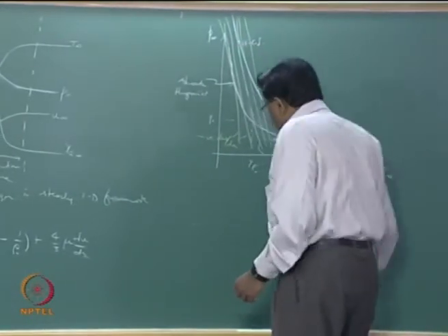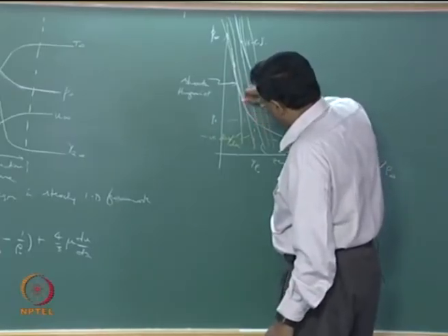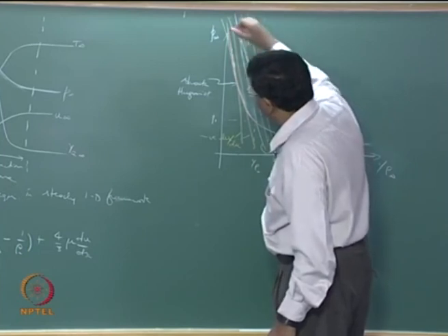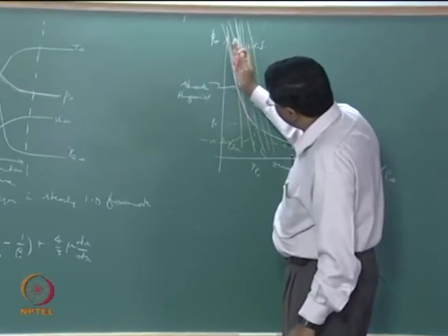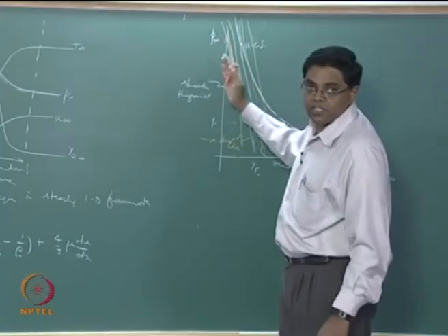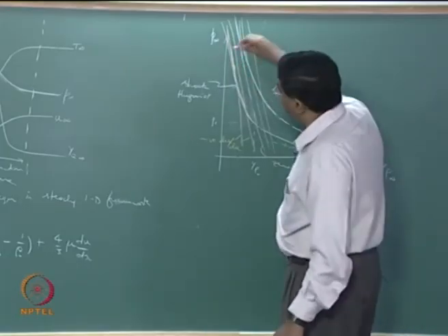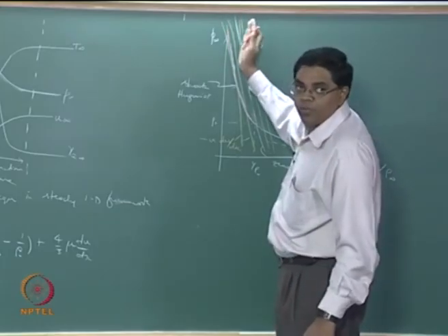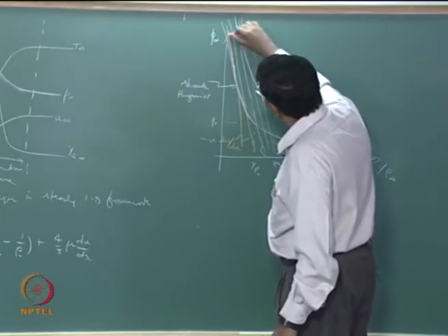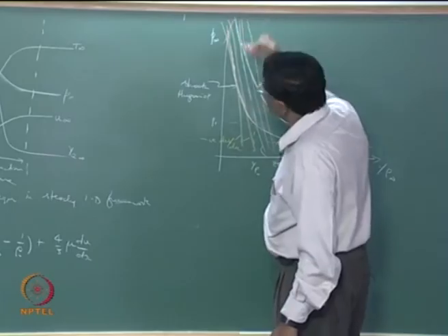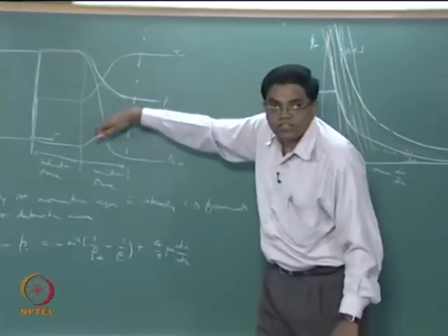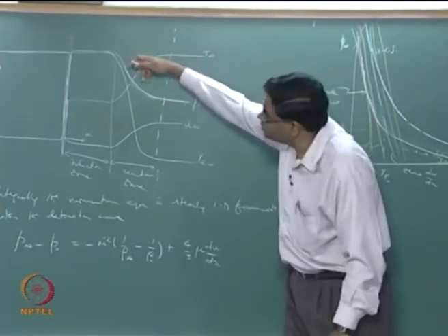That means your path would now go along the shock Hugoniot as much as possible. You see, the moment the shock Hugoniot deviates from the Rayleigh line, like in tangent Rayleigh with a negative du by dx, your du by dx begins to grow back to 0, and then it begins to go away from there and reaches your 0 du by dx, and then you have to go through the positive du by dx region, when the pressure begins to fall again.